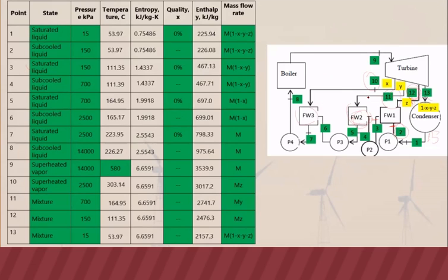For the mass flow at the different points, first we are going to look at point 9. It enters point 9 as one, no? As a whole mass of steam. Then it will be extracted at point 10 as x. So meaning the flow at point 10 will be mx. So we have here point 10. It should be mx here.